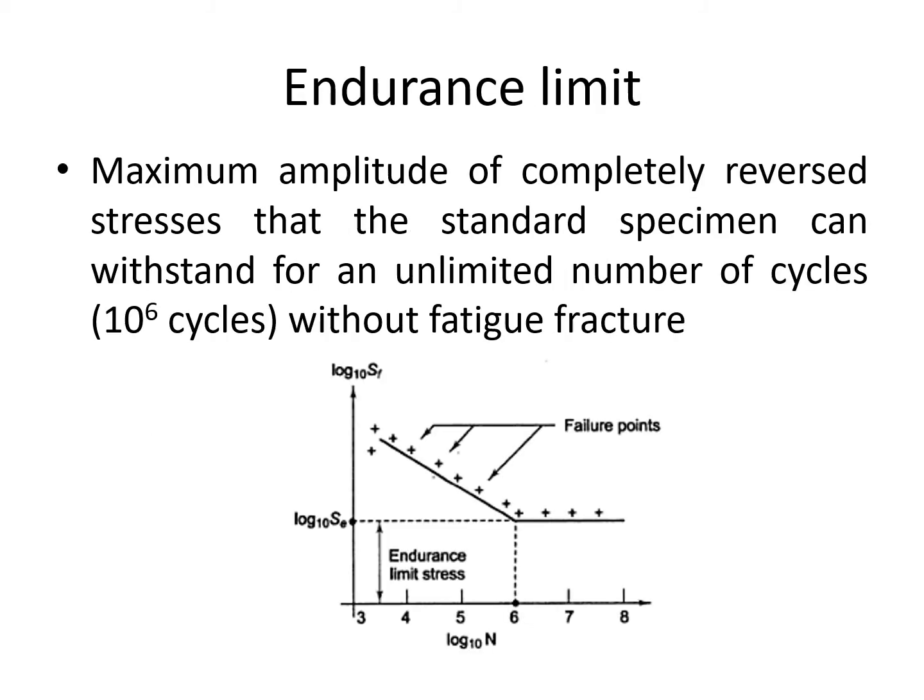Endurance limit. Just before, I said cyclic loads reduce our strength, but that's not always true. If you are applying cyclic load up to 10 power 6 cycles, you can see from this graph that initially the strength is reducing.